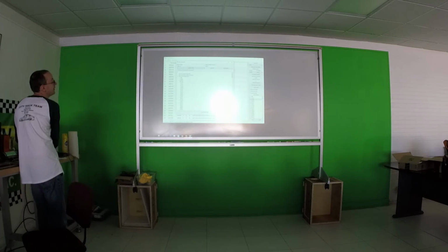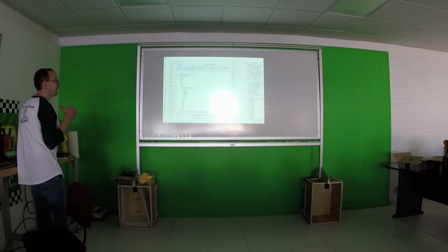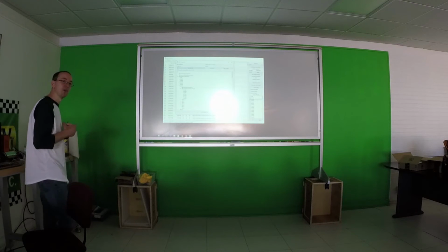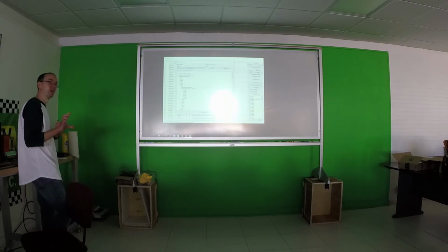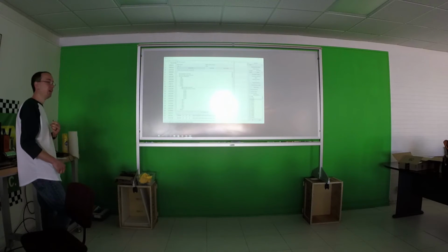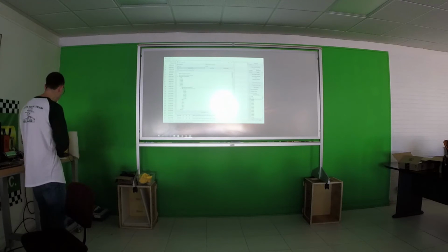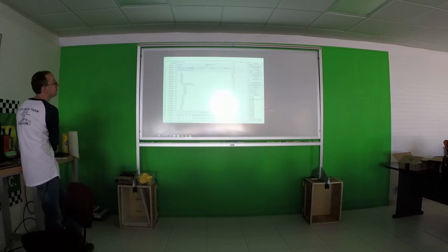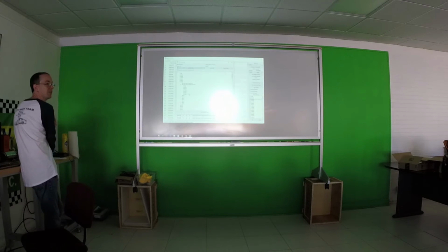But sometimes you find data. For instance, on Byron's Transit Connect, we were looking for the heater message. The heater is 4 zones of heat plus the pump to turn the heating pump on. So we knew we were looking for about 5 bits that might be toggled when those zones turn on and when the pump turns on. We actually used this to look, and I did get pretty close to finding it until we eventually figured out that we had a DBC file that had the data anyway. Oh yeah, that's right, we got a DBC for that. So we just gave up and used the DBC file.